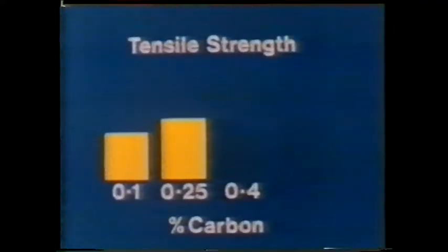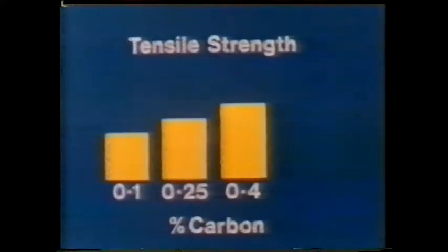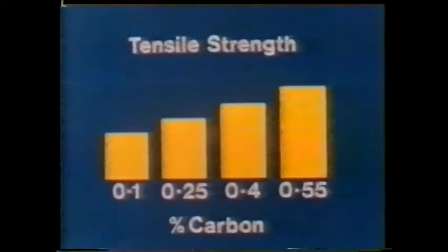0.4%, even more strength, and 0.55% carbon, stronger still. So it seems that the more carbon there is in the steel, the greater the tensile strength. But what effect does increasing the carbon have on the other mechanical properties of the steel?